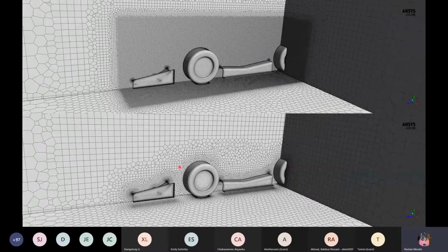In this example, I made a couple of meshes, but I've just shown you the two extremes. This is a polyhex core grid. Generally, you try to keep one thing as constant as you can, so I've tried to keep the sizing on the actual elements as similar as I can. This is an FSAE car, by the way. And you can see the major thing that I've changed is the cell sizing around here.